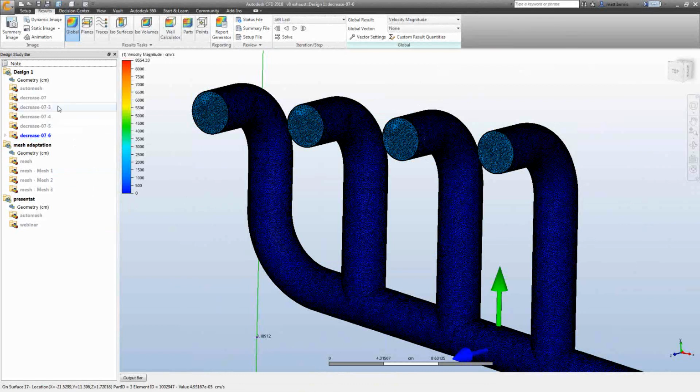I think I set these up before I really saw the results. So I ran them all, but you'll see your results probably aren't going to be changing in my last 3 scenarios. And again, this doesn't quite match what I put in the PowerPoint because I have more scenarios here. Now, what was really cool was, although I don't jump to mesh adaptation every time, I kind of like doing things my own way, the mesh adaptation got mesh independent results in like 730,000 elements, which is kind of embarrassing. They almost have me by a factor of 10 there, almost.